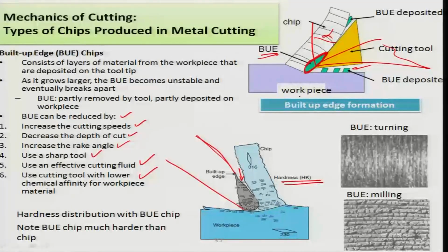Hardness is as high as 704 HK Knoop hardness recorded here in the case of this built up edge, whereas the standalone chip does not have hardness more than about half the value, about 372, and so is true for the workpiece surface. No wonder then that the built up edge is plowing on the surface and is able to successfully cut metal as a virtual tool surface.